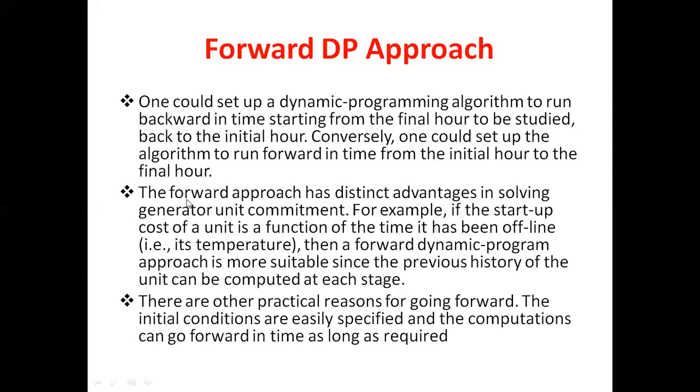The forward approach has distinct advantages in solving generating unit commitment. For example, if the startup cost of a unit is a function of the time it has been offline, then a forward dynamic program approach is more suitable since the previous history of the unit can be computed at each stage.